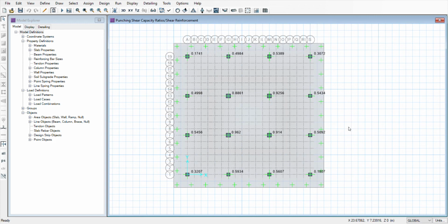Let us consider, I have made some assumptions. SBC equals 300 kilonewton per meter square and allowable settlement of 1 centimeter, and I have got the subgrade modulus of 3 multiplied by 10 power 4 kilonewton per meter cube, and the strips of 0.25 times 18 meters, that is I have got 4.5, it is approximated as 4 meters.